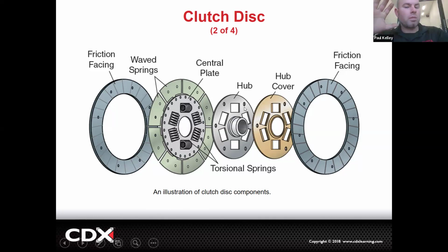And that's why the hub is going to be smoothed out, because we're hitting those torsional twisting forces up against the spring. The spring's going to absorb some of it at least. I don't know how much, some of it. And then the hub is going to turn a lot more smooth, a lot more dampened. So what's going through the transmission is smoothed out power. That's why we have these springs. That's how this setup really works.